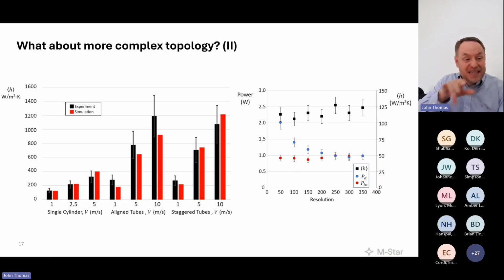And again, this was the same correlation for semi-empirical theory I used for the isolated vessels, right? And why does it work? Why is it topology and operating condition agnostic? Because it's not appealing to topology or operating condition. All it's appealing to is the local turbulent physics surrounding each individual patch of wall, okay? And that semi-empirical model doesn't care what color the agitator was. It doesn't care whether that was on the back side of a tube or the front side of a tube.